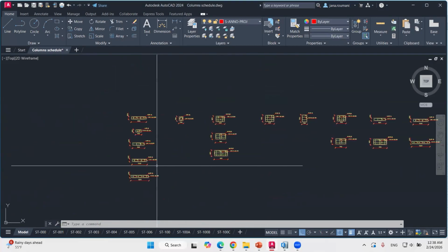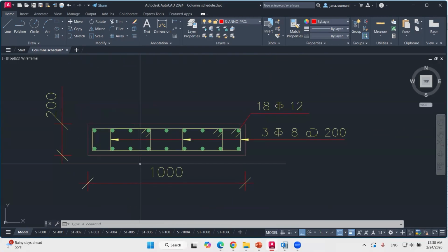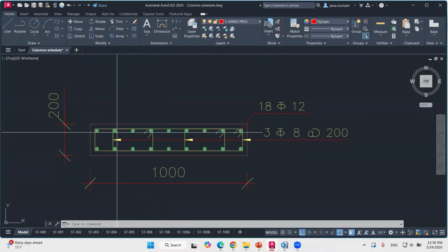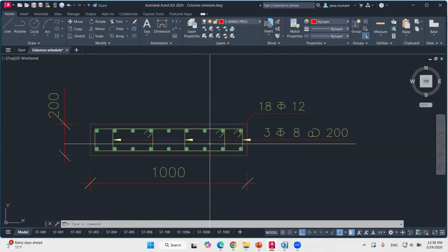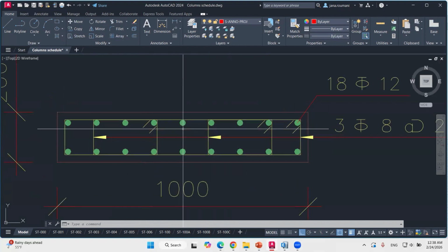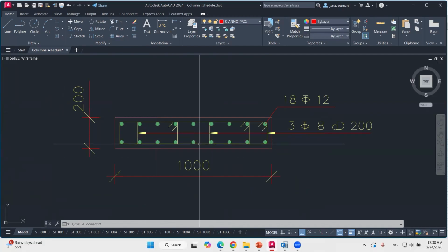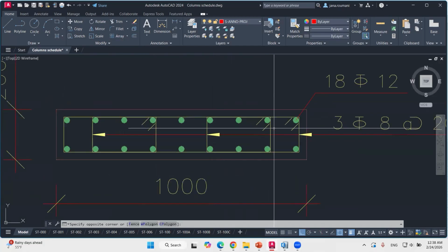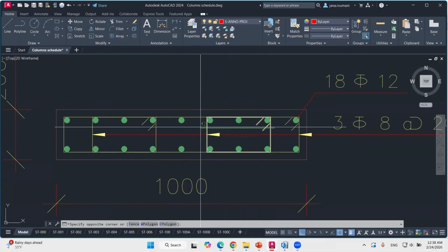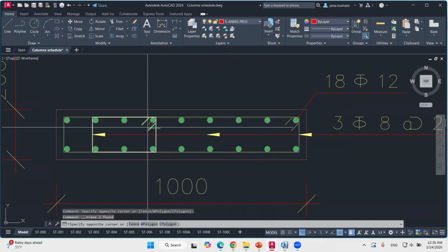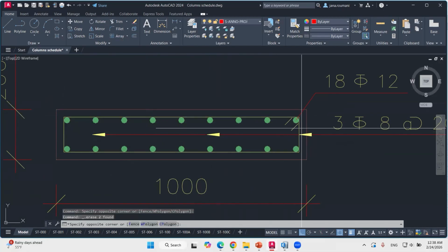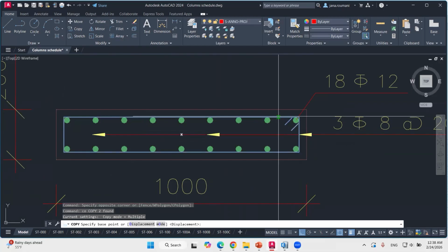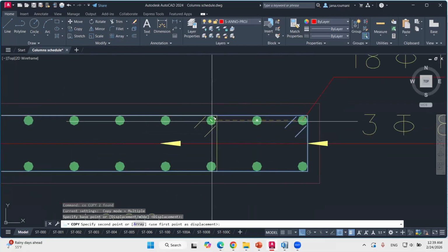So now just to see some stirrups arrangement. As we mentioned, we need to keep them symmetrical and without two bars in a row unconfined. So here we have this type. Let's see if we can do another arrangement. For example, if we can try this one.